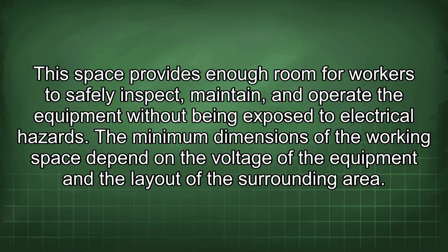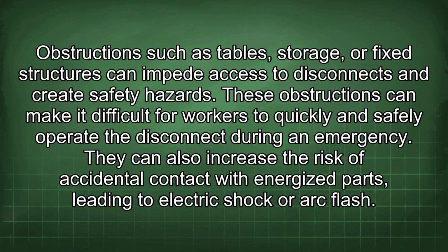surrounding area. Obstructions such as tables, storage, or fixed structures can impede access to disconnects and create safety hazards. These obstructions can make it difficult for workers to quickly and safely operate the disconnect during an emergency. They can also increase the risk of accidental contact with energized parts, leading to electric shock or arc flash.